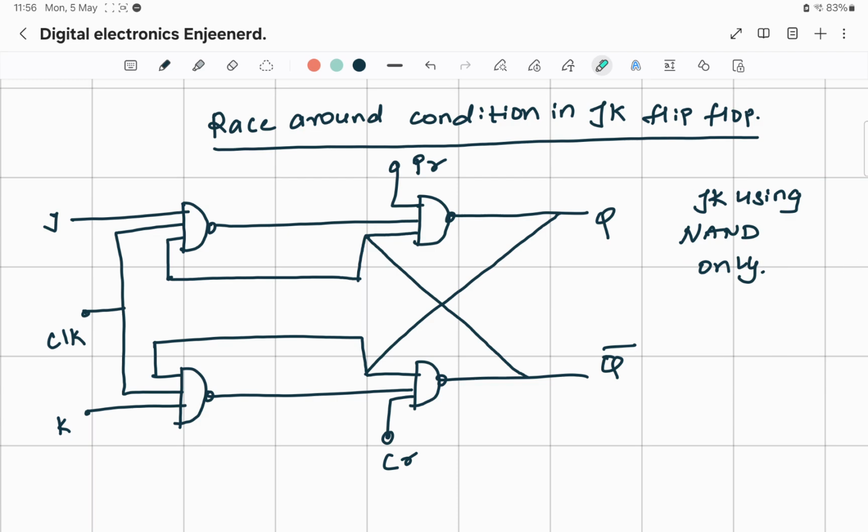So what is the construction? Same, you have NAND gates to provide our inputs, which are J and K. There is a clock which is connected between both of these signals. And if you remember, J had one more input coming from Q bar, right? So this is how the connection we did. Same thing we are doing, just that we are connecting it internally, not from outside.